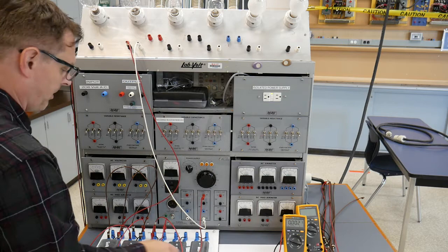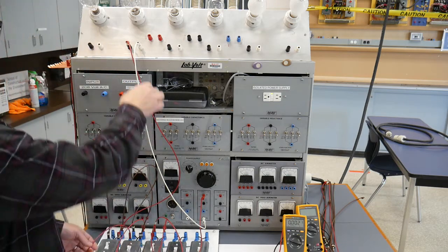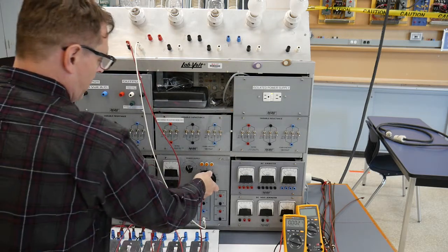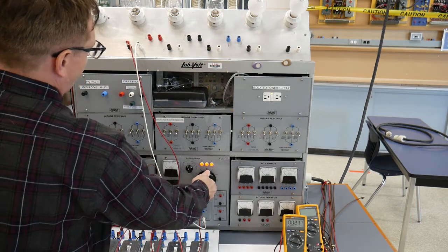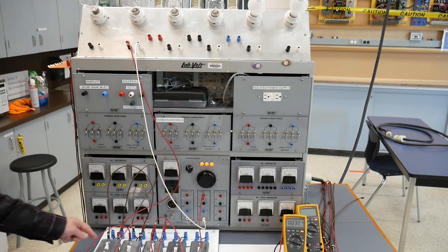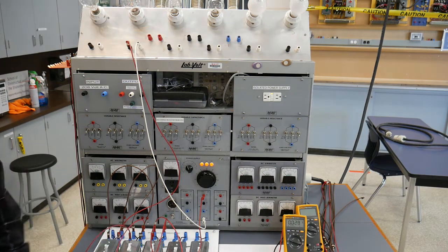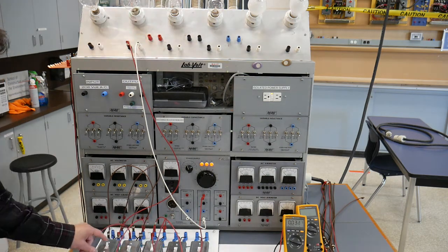We had our hot coming to our first 3-way and then going through all of the travelers and the switch leg up here and returning back to neutral. So if I've wired it correctly, I should be able to turn this guy on, turn my volume up. I've got everything in the off position. I can now turn that switch on, that light goes on, turn that, it goes off. Turn this it goes on, he goes off. Just keep moving through the process.